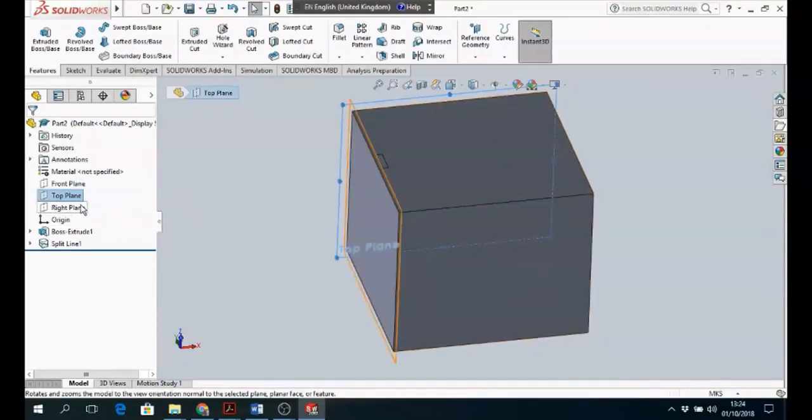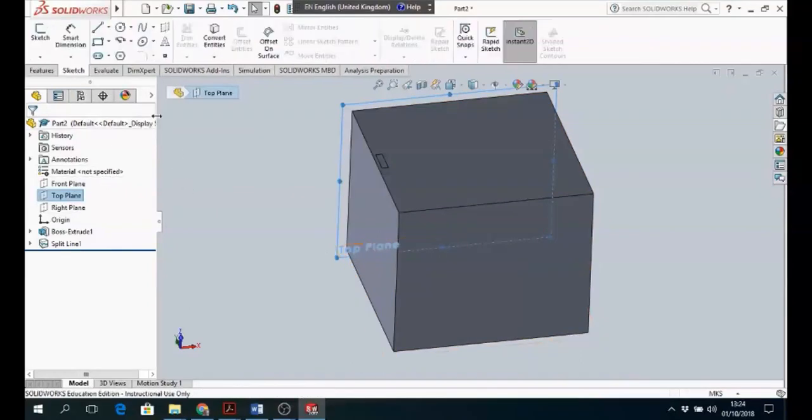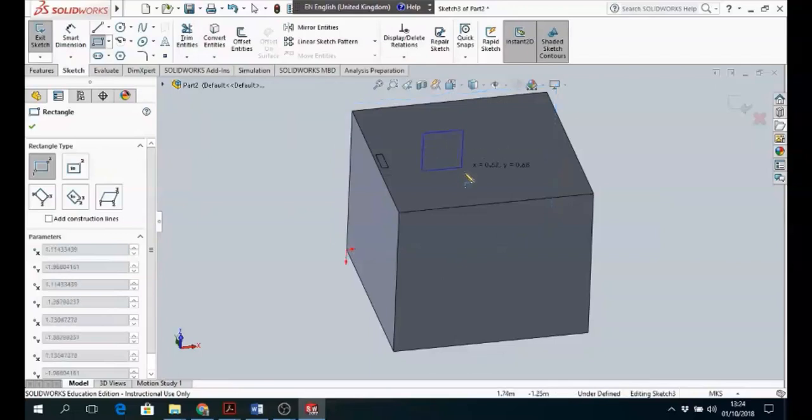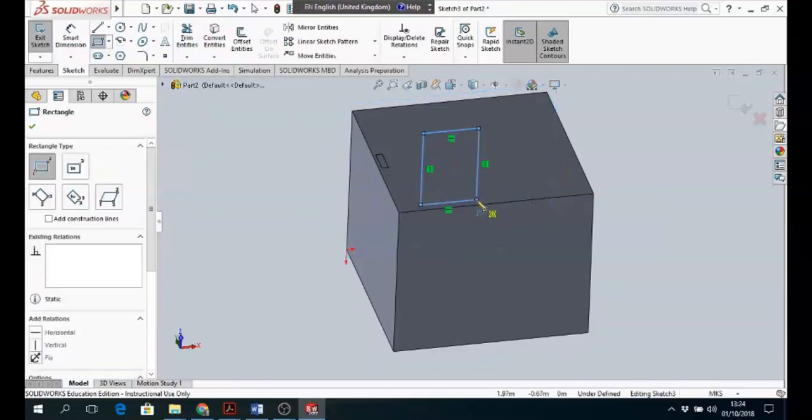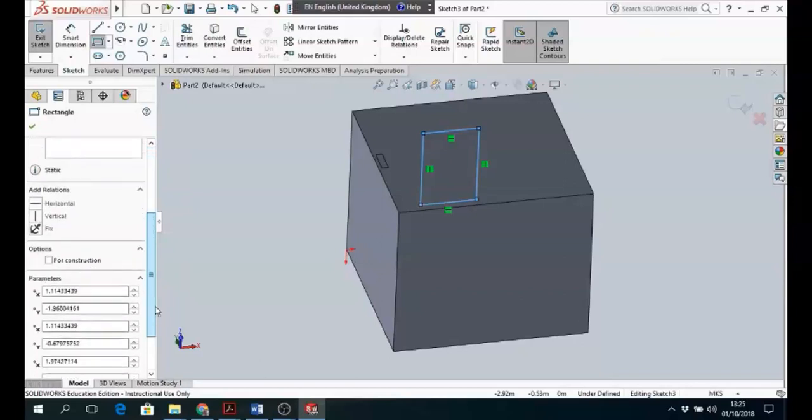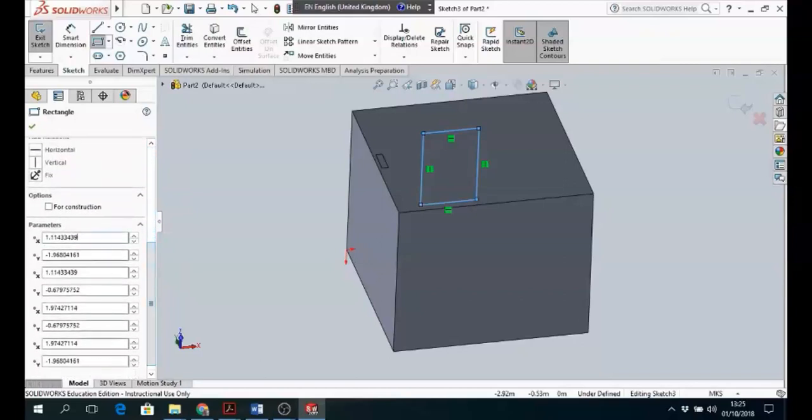It saves me having to create a new plane for that. So if we select one face here, we're going to do the window first, in around the middle of the plane here. Once again, we can set the dimensions as needs be. We see that down here the dimensions of the vertices of the corner come up.